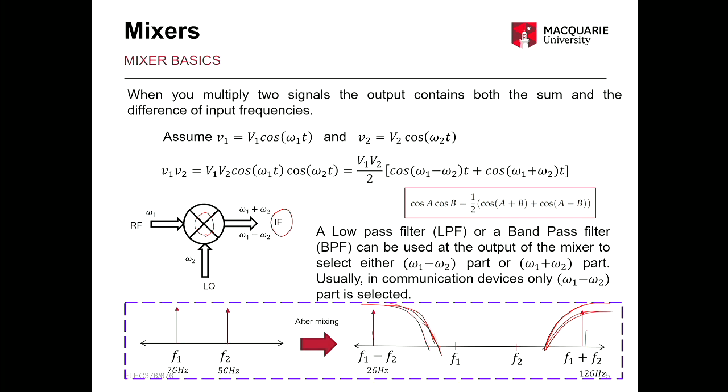There is an equation between the wavelength and the size of the antenna that you need to use to transmit that frequency. The size of the antenna is lambda divided by 4. So if you have a 1 kilohertz signal, you can find the wavelength lambda, which is the speed of light divided by the frequency. That's quite a long number, it's kilometers, and 1/4 of that is kilometers. So that means you would need an antenna which is kilometers long, which is not possible, right?